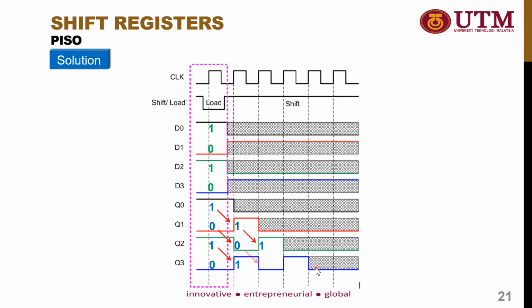So at the fourth clock cycle, you can observe all of the data that you wanted to transfer, where you are getting the same input data which has been connected to D0 until D3, 0101, and after four clock cycles, you can observe the output of 0101. This is a PISO shift register where you have the parallel input and the serial output. So you can transfer 4 bits at a time, but you can only observe 1 bit at a time.